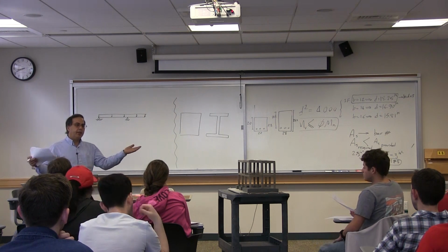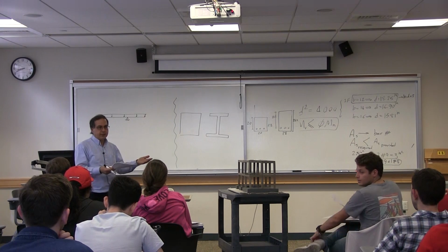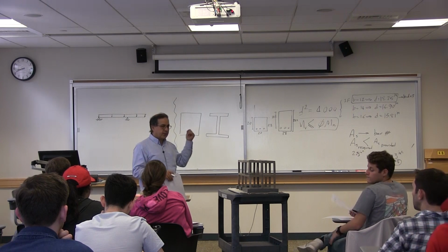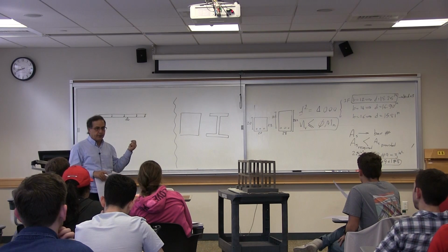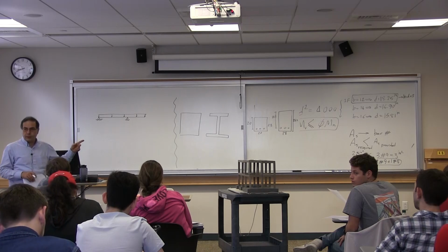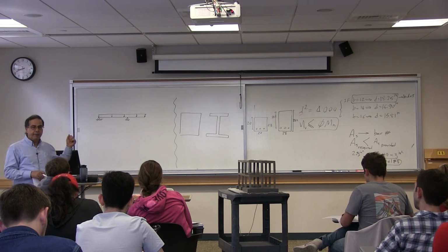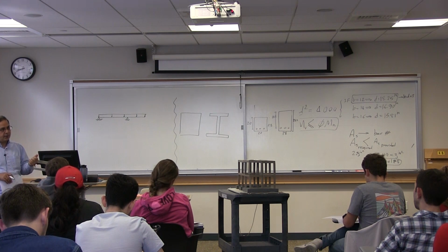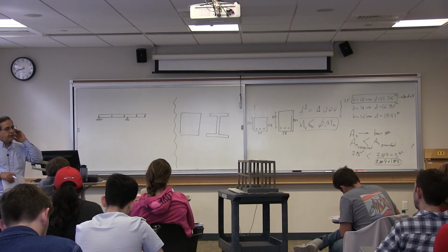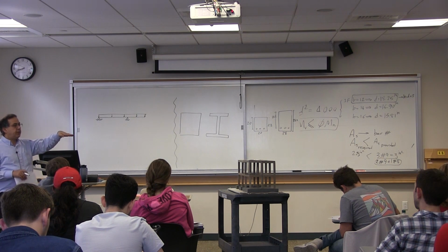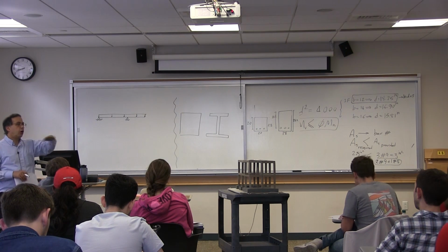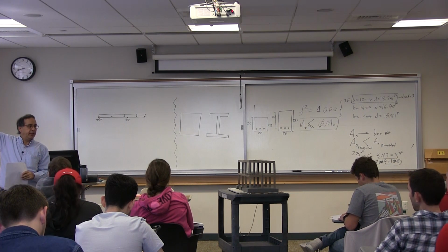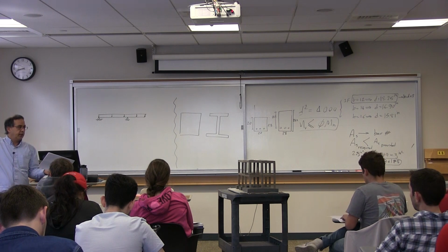They are practically independent. You are designing two different sections. As he said, the only dependence is that the size of the cross section remains the same. Why do you think the size of the cross section would remain the same in practice, based on what we just discussed? You want level beams. You can make the beam deeper at the bottom, which at the top would be level. I really don't care if this beam is going down a little bit here, it doesn't concern me.